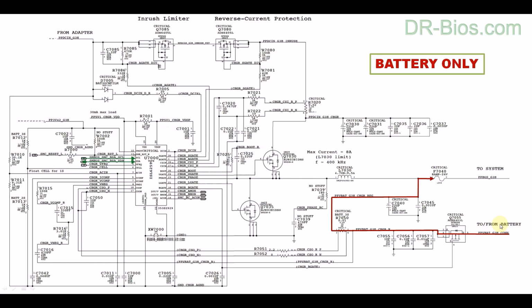So it starts communicating with battery by SMBus protocol, and receives all data of battery, and it will use this data when necessary. And when adapter gets plugged in, it uses these data to charge battery with the help of charging IC.